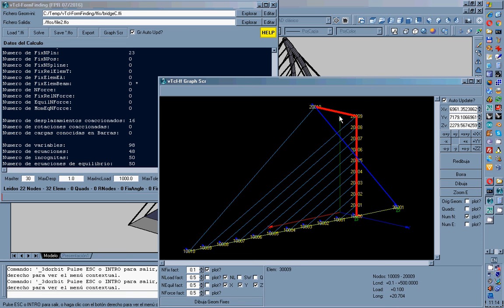You see that there's a kink here because I don't need to be precise in the construction of the geometry. The mast I'm introducing as a starting geometry as a vertical mast, and then the last node is going to the position where I want to have that node, and then during form finding the software is going to move all these nodes to the proper place.